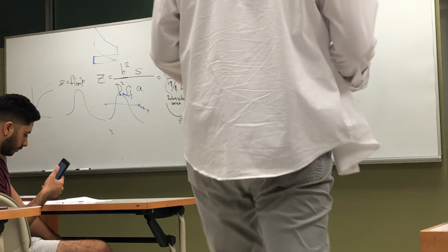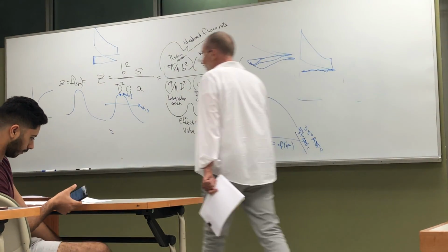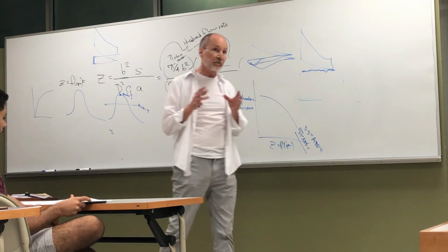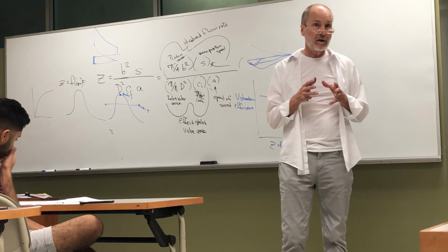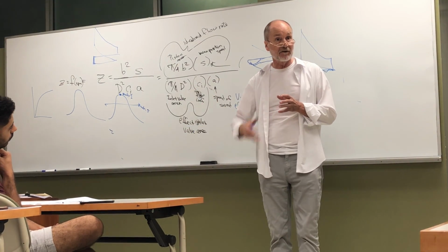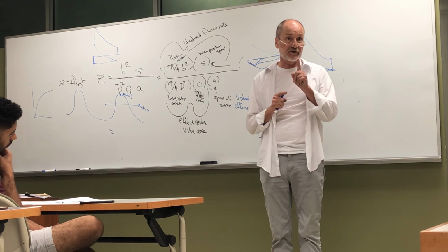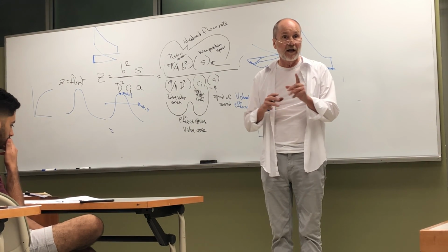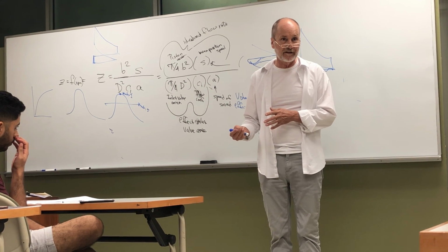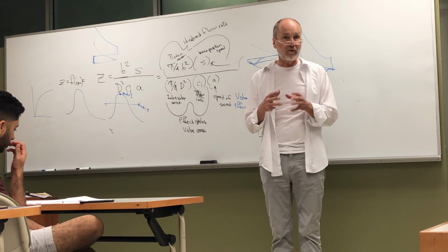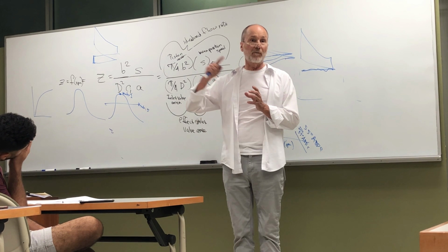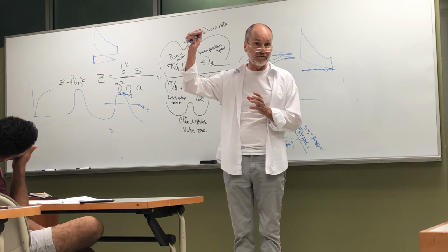No. Once you hit the speed of sound, the mass flow rate, if you don't change the upstream pressure, stays constant. But your volumetric efficiency is a function of two things: how much space you're creating, which is a function of RPM, and what the actual flow rate is. The actual flow rate's constant, but as you go to a higher Mach index number, you're sweeping out more and more volume, so the volumetric efficiency goes down.